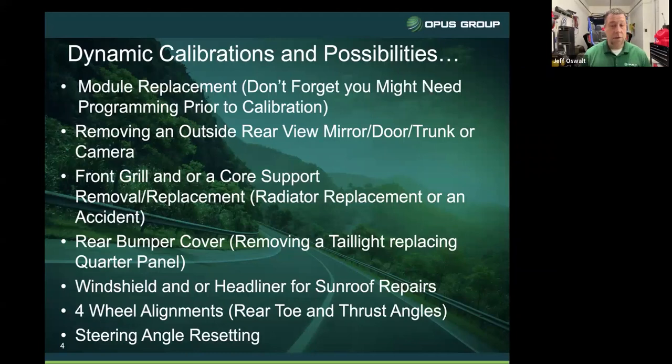Windshields. Anytime a windshield's getting replaced, all the OEs are going to recommend the OE glass. I've had a few Jaguars where I was trying to do a dynamic camera calibration on a Jaguar. It will not calibrate because the glass was aftermarket.